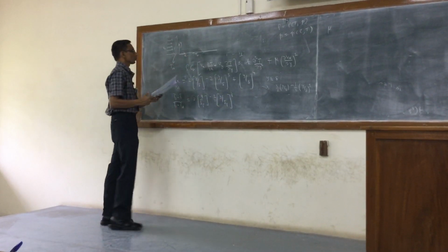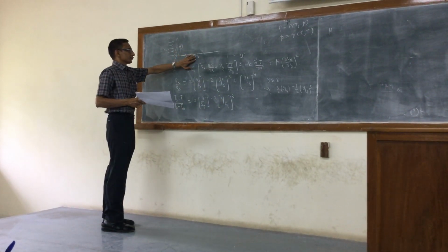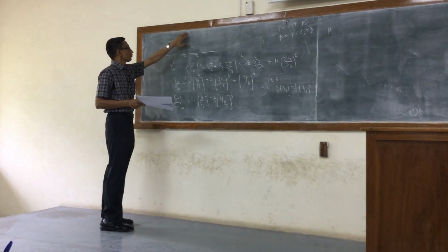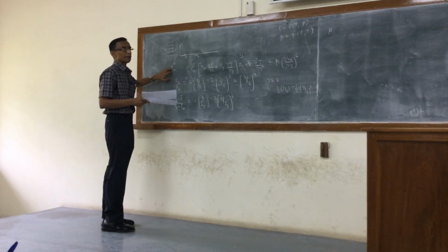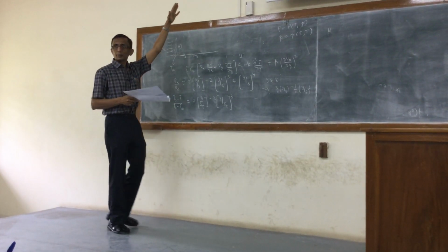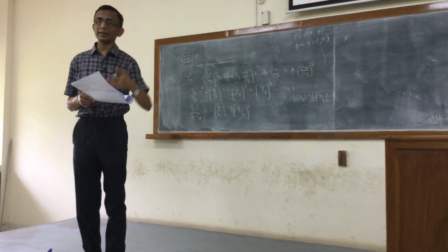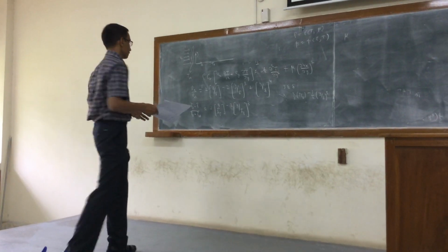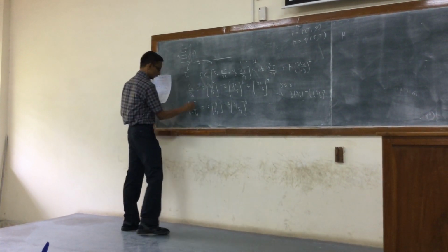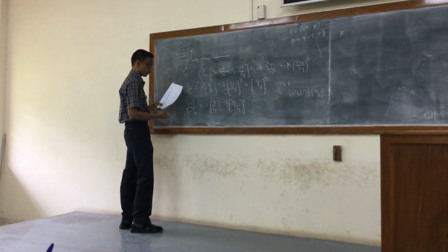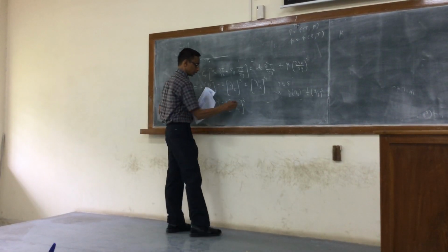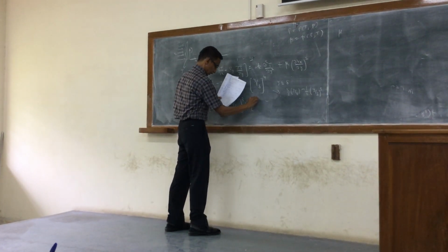The thermal boundary layer is defined as follows. This is T0, right? And finally the temperature is going to be T infinity, the bulk. Wherever that reaches close to T infinity, say 99% of it, this difference is what is referred to as the thermal boundary layer.